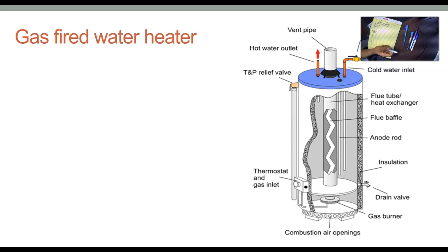So usually it's 80 degrees for swimming pools. That's what we find comfortable. And if you go below, probably if you are doing an Olympic pool where the people are doing a lot of activities, probably 78 is more comfortable because people will be doing a lot of movement.